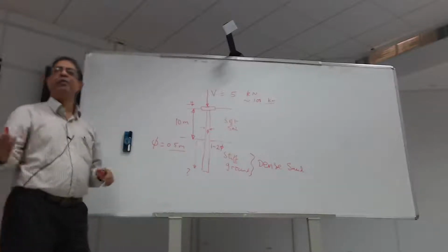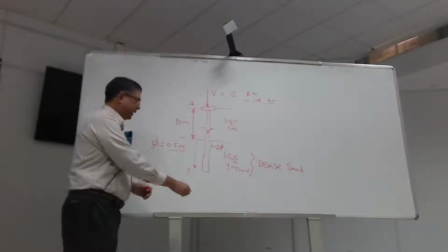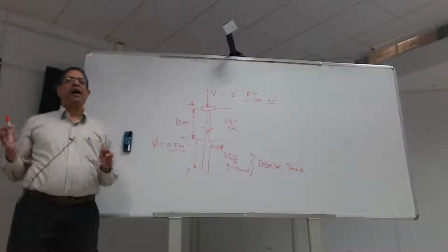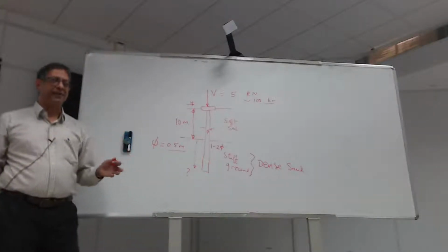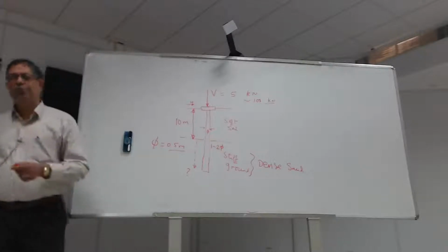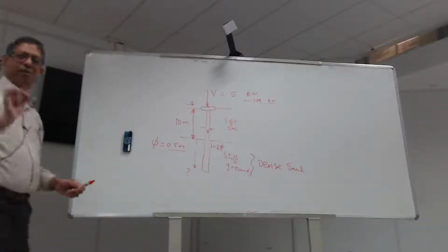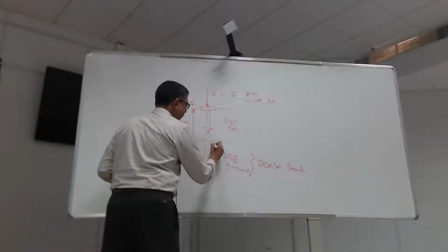In other words, like what we were saying yesterday, below the length of fixity, even if I push this to the center of the earth, the pile has no effect. So you only want to go up to the length of fixity. There's a guy called Andrew Bond who did some work on this, and he recommends between 5 to 7 diameters. So this should be of the order of, let's say, 5 diameters.